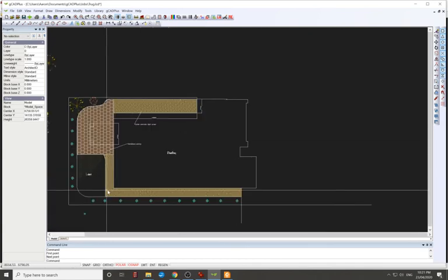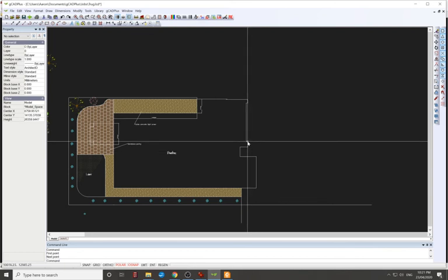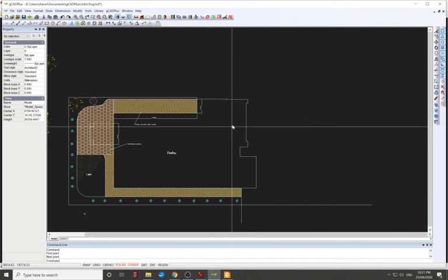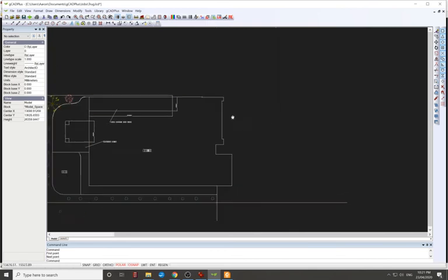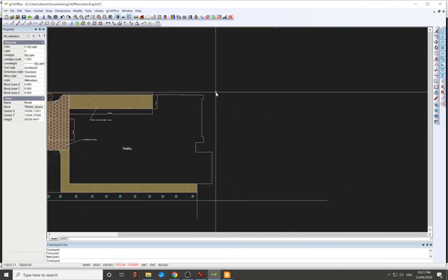I don't think the house is running on, I mean, it's very possible this is running 40 mil on an angle. Overall, that could buff out. I've measured straight from there, but every time you have 10 mil render on there, there's your 20 mil there. I could have measured off the brick here. There was a little bit of an angle, and it adds an extra 10 mil. There's another 20 mil. Could be 10 mil on that brick, anything. So 40 mil in the scheme of things, I'm pretty happy about that. So it's not much to be concerned about.